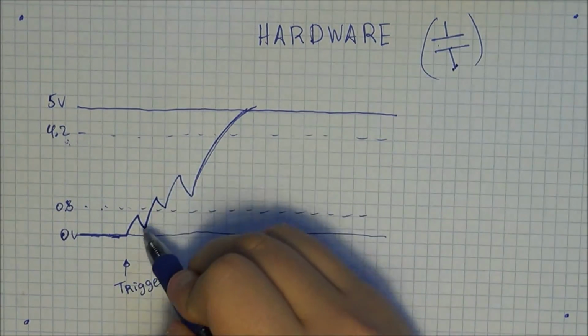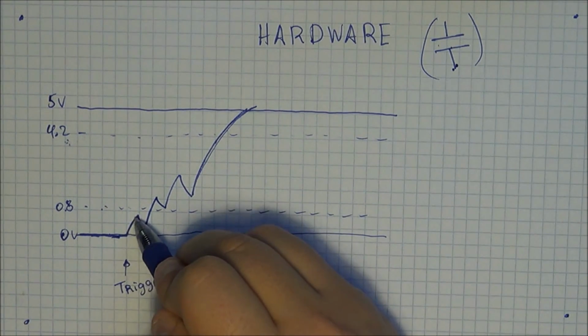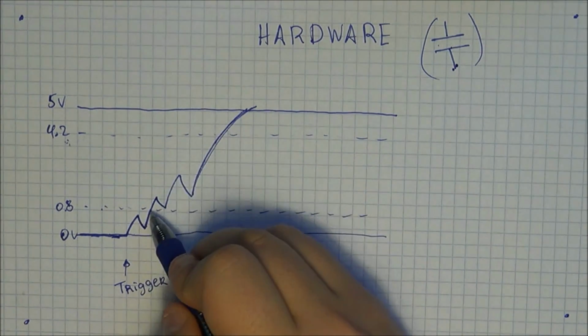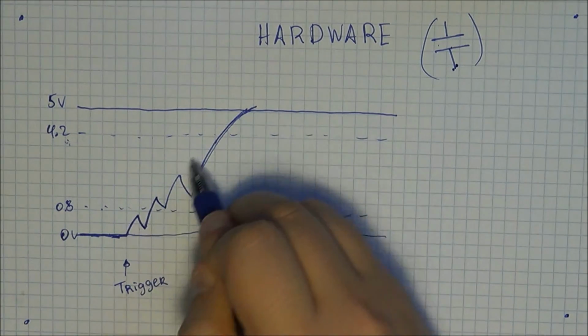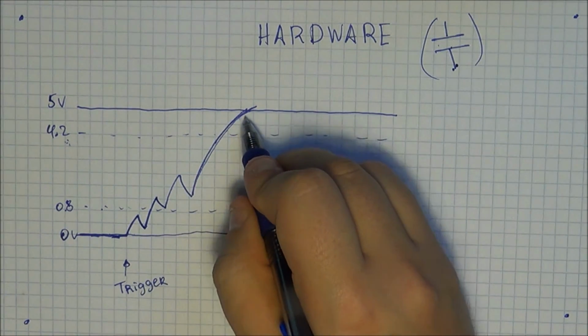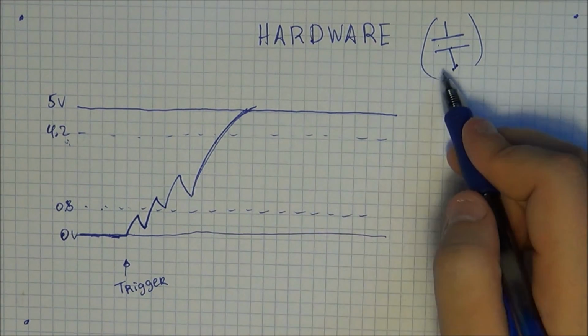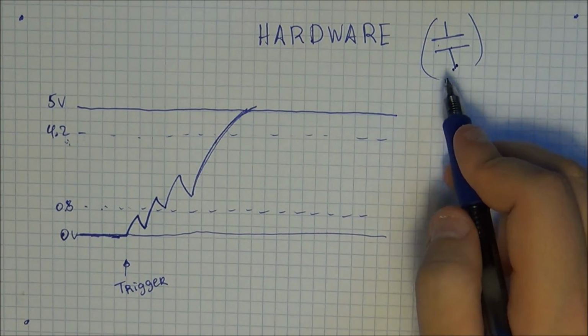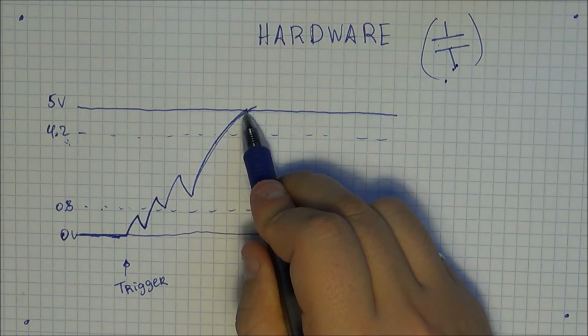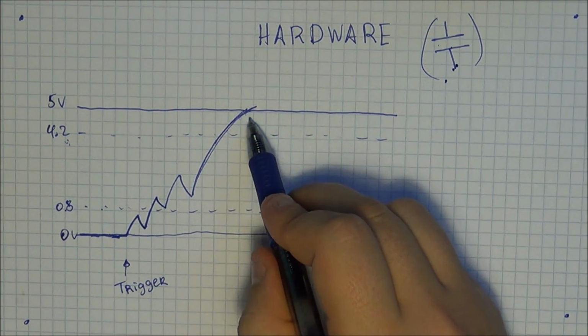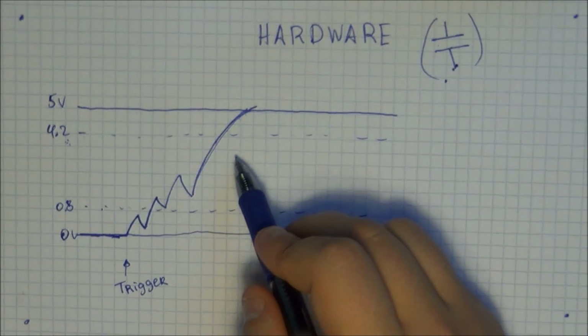So as you can see, this capacitor is going to prevent these spikes all the way up to 5 volts, and you're going to get this sort of smoother transition, and it's only going to transition obviously based on your capacitor value. It's going to transition much slower, but at the same time you will detect that full transition much more accurately.